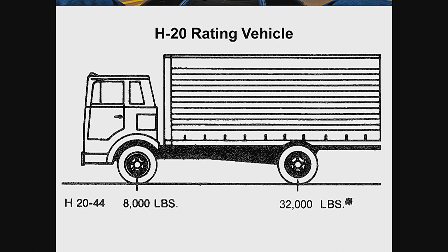What that looked like was 8,000 pounds on the steer axle, 32,000 on the second axle. Now these are simply design trucks. They don't exist. Maximum axle load is 20,000 pounds on an axle. So these trucks are just for design purposes. They're not for posting purposes at all.